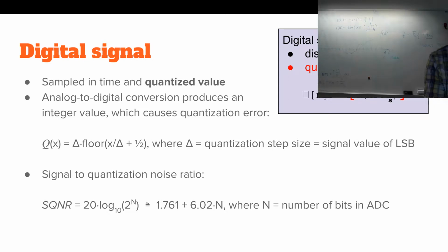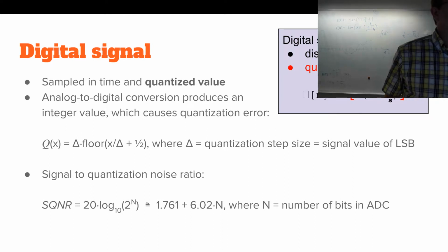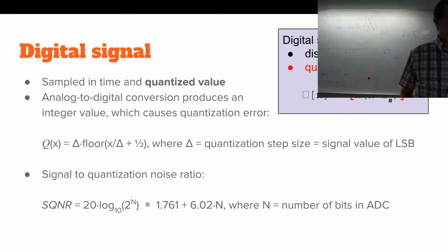It basically tells you something about how many bits you should have on your A to D converter, given the dynamic range you are reaching and the noise floor of your sensor. So no need to add bits if you are adding noisy bits.